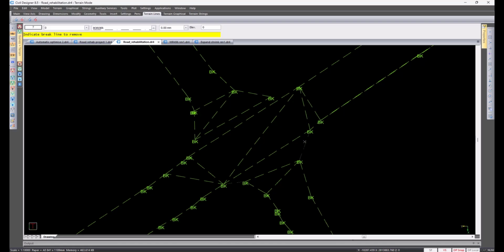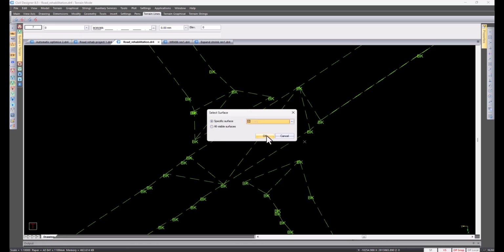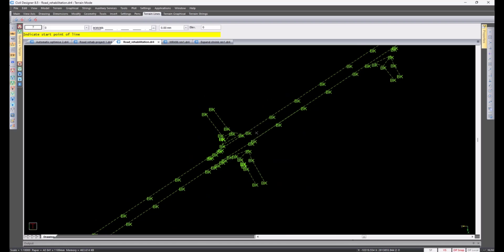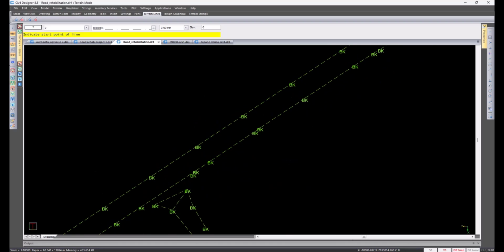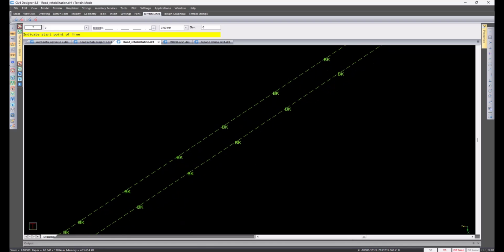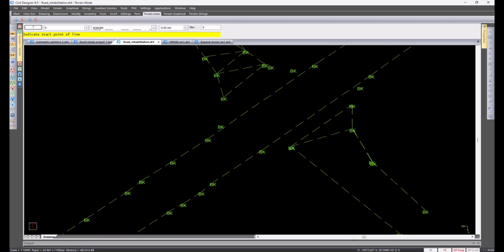You can also use our remove crossing lines feature, that new function. So it's model, break lines, remove crossing. So this would be surface 3, and then you can just draw from one point to another. A bit quicker working like that. The test for this would be when you actually run the point string to see that it runs from the start to the end point.